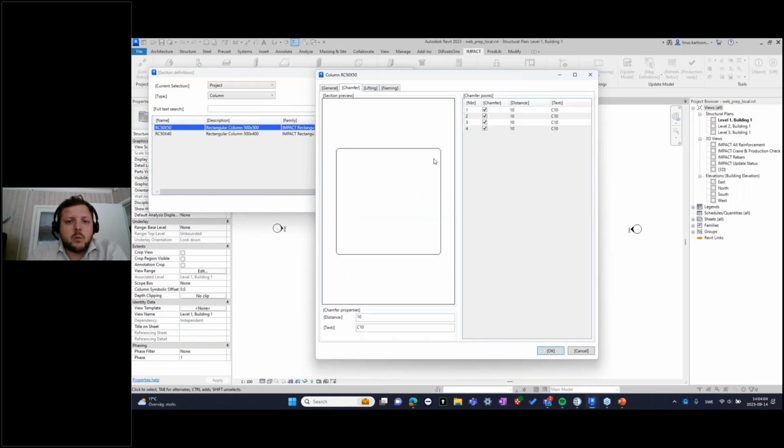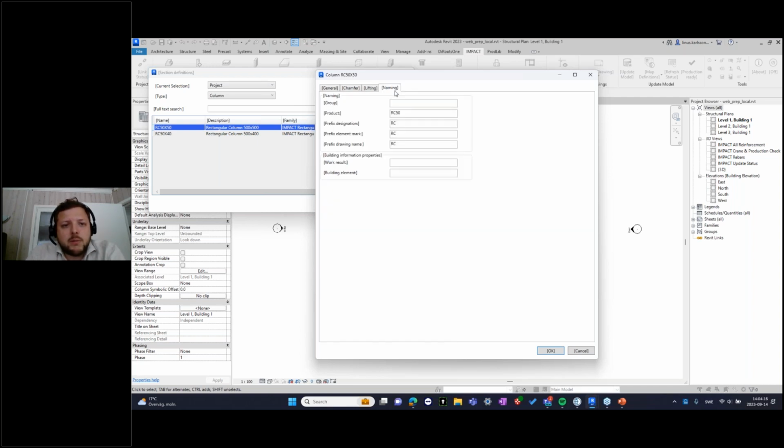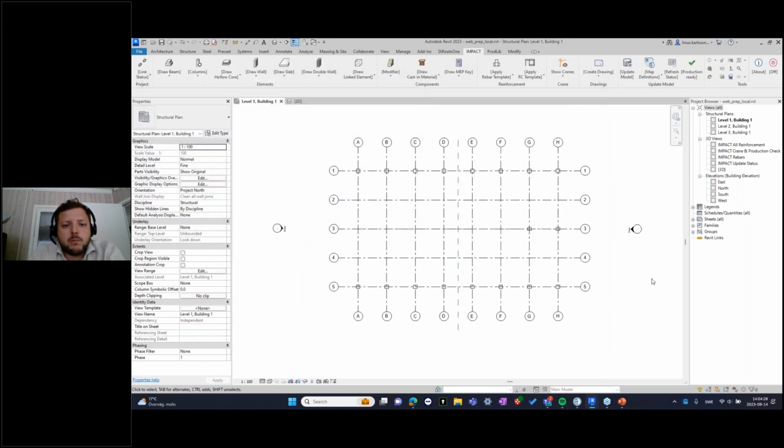And we have decided what type of chamfers we will have, what lifters and so on, and when and where they are going to be used, depending on both mass but also the size of the element, and how to name both the element, the shop drawing, but also some product naming so that we can filter later on, mostly in the production software.